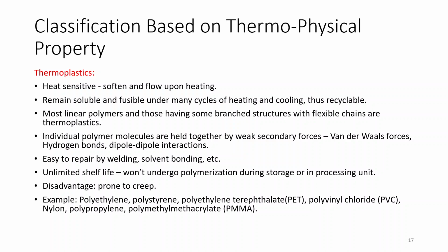Next is classification based on thermophysical property. In case of thermoplastics, you have heat sensitive polymers, which soften and flow upon heating. So you can keep on reheating your material, soften it and provide a different shape to it. It remains soluble and fusible under many cycles of heating and cooling, thus they are recyclable.